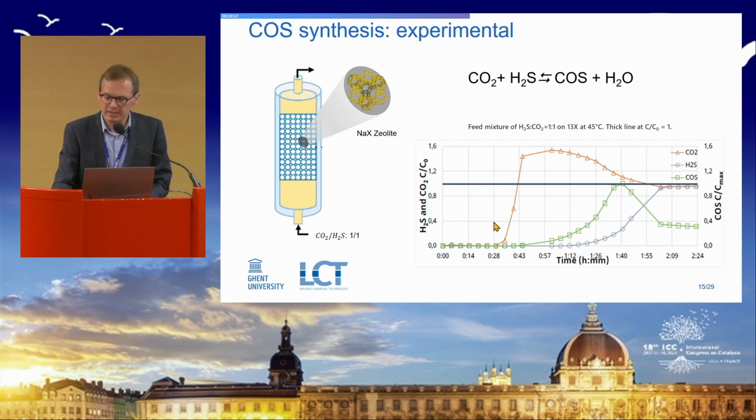Here you see an example result of a transient experiment where we started with an empty bed. It takes about half an hour before the first components start coming out, and the first one to come out is CO2, which, until there is nothing else, is weakly adsorbed on the catalyst.